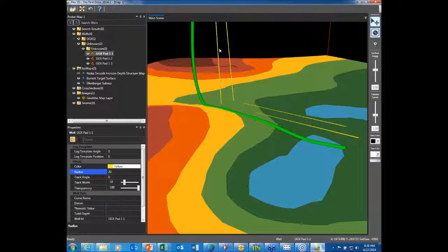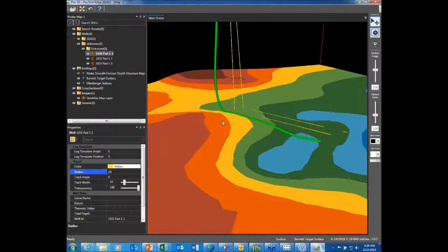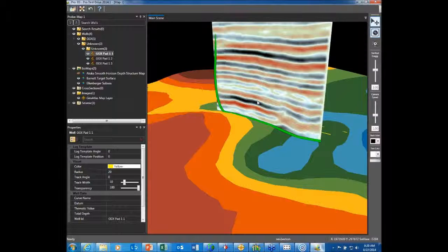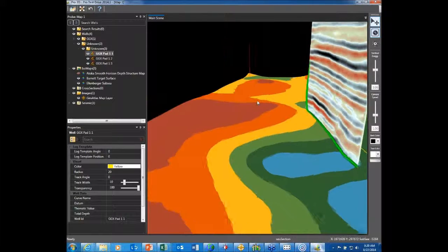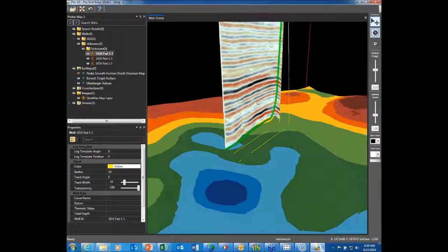These 2 other wells were part of the field planning well plan, and they landed as a heel point on that surface and truncated or ended as a toe point right here. So these would have to be put into LMKR Well Planner to get this drillable solution right here. Now, I've also done an interpretation in SeisVision, and I built a velocity model, and I'm using that velocity model now to dynamically depth convert a seismic backdrop. And I can put the seismic backdrop and wrap it right along the borehole so you can compare your geometry or borehole to the drilling through the seismic volume.